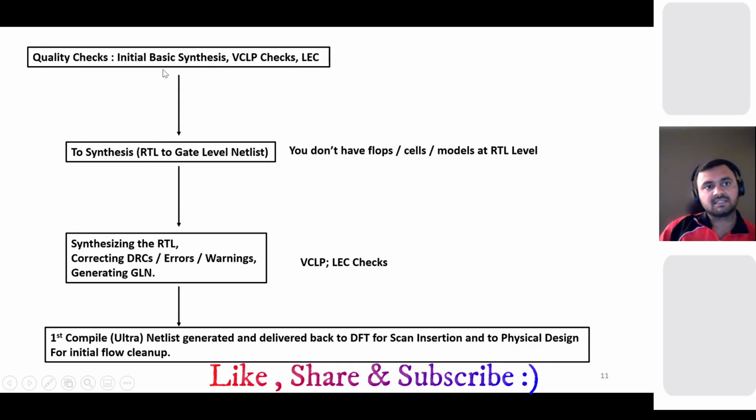Then we'll do some quality checks here. Once you have inserted your DFT logic in the RTL, you will do the basic synthesis, then low power checks and logic equivalence check, that is LEC. In basic synthesis, we make sure that whatever we have done is at least linked to the library. Otherwise, the synthesis team will get the error and you have to redo the process. So to avoid that, we do the basic synthesis.